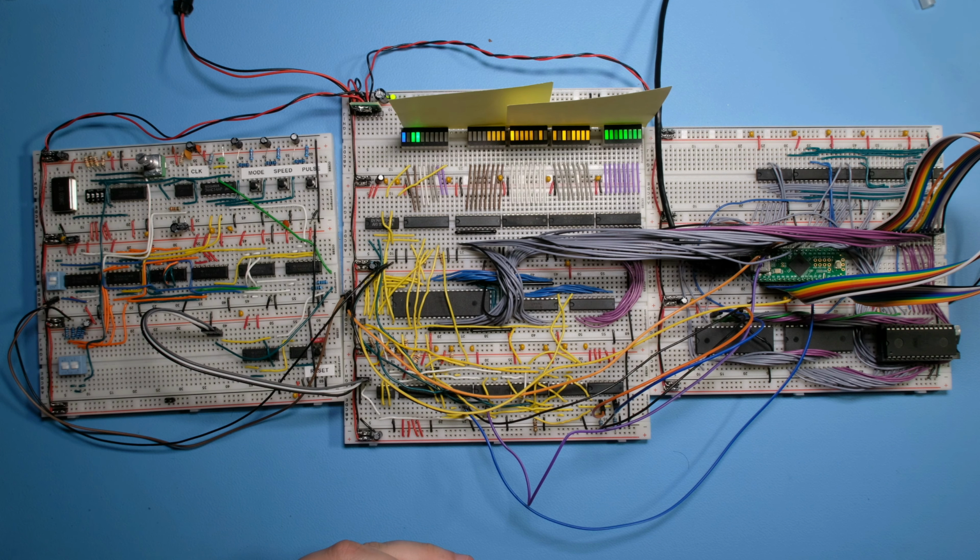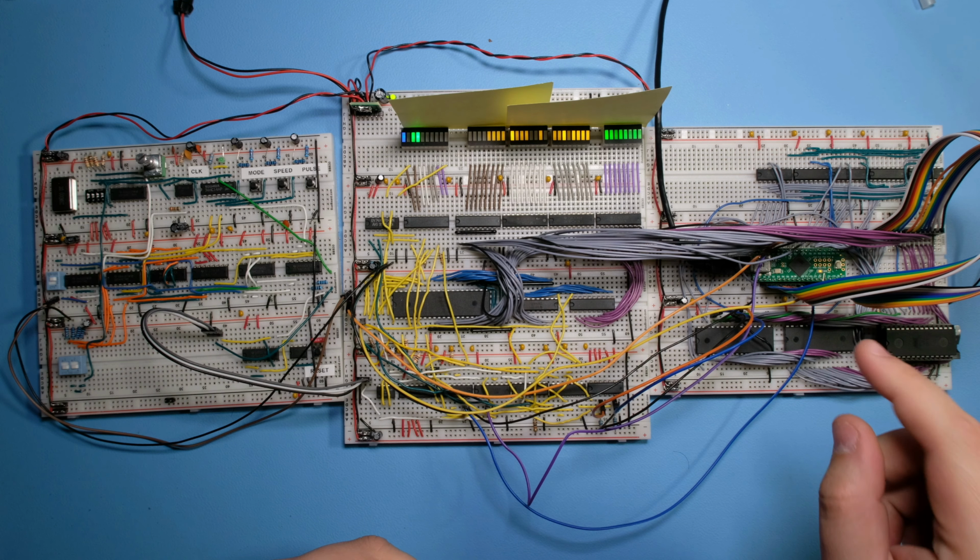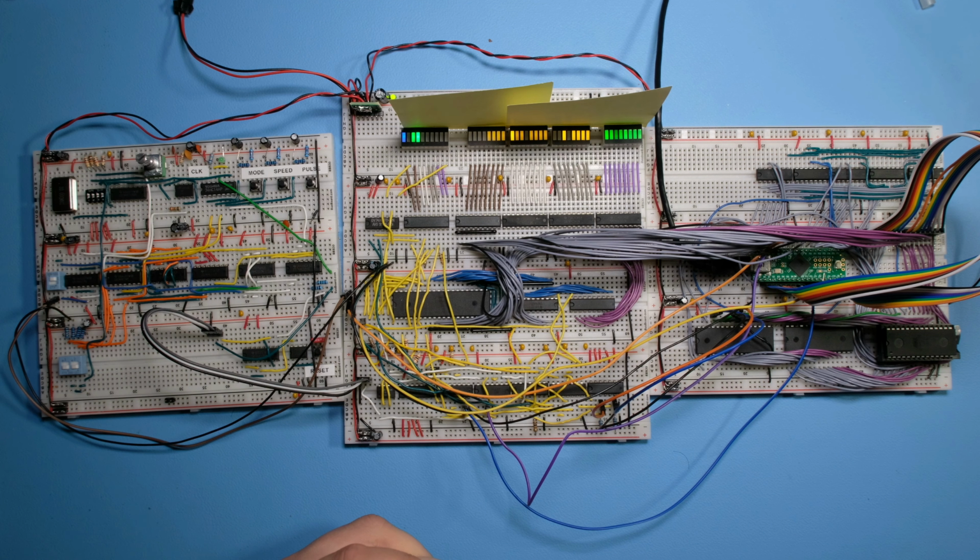One of the things I'm thinking about doing is having the Teensy send only bytes through the serial connection instead of formatting it into readable characters, and then having a program on the computer that's able to read this stream of bytes and format it on the computer. And this should speed up considerably the speed at which the Teensy is able to transmit data and so rotate the clock. But that's the subject of another episode.